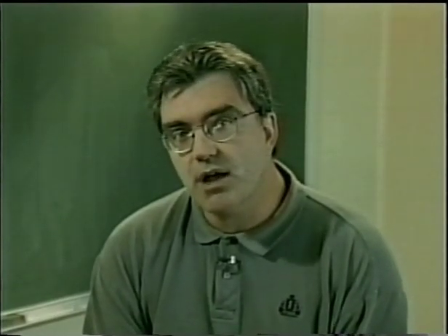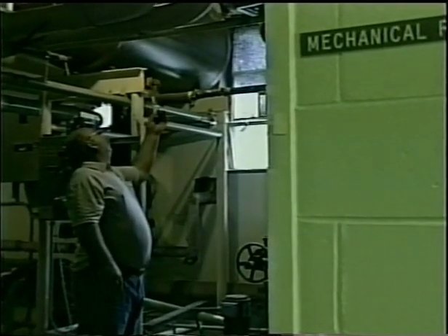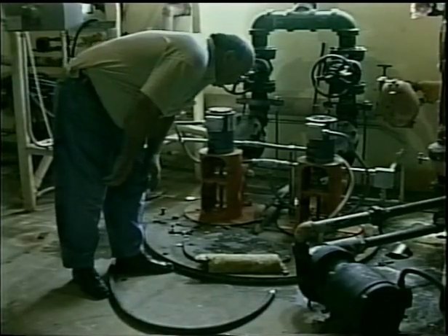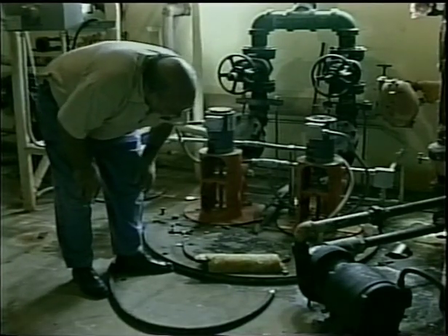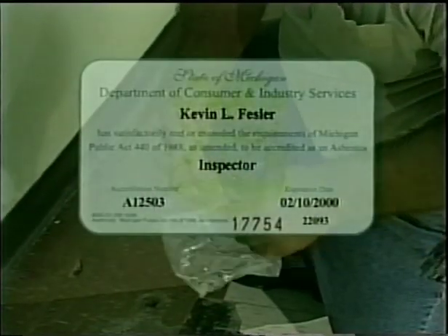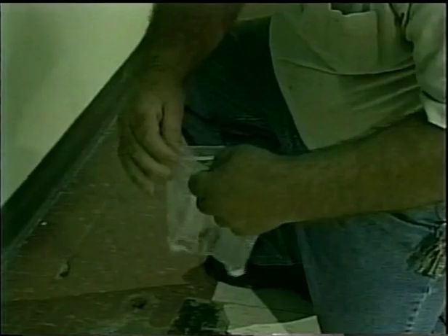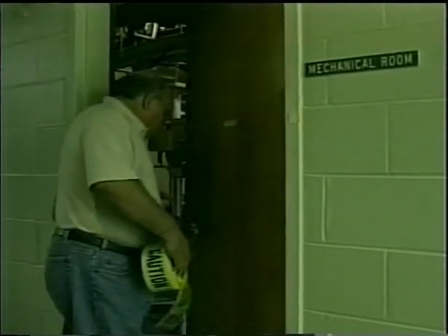Now that you're familiar with where asbestos is in your facility, let's talk about how to avoid exposure. If you do not know whether something is asbestos or not, assume that it is until proven otherwise. Remember, in order to avoid being exposed to asbestos, you must be aware of the locations. Remember, you cannot tell if floor or ceiling tiles contain asbestos just by looking at them. If you have questions about whether or not a material is asbestos, never try to take a sample yourself unless you're licensed to do so. Contact the people in charge of the asbestos program in your facility.